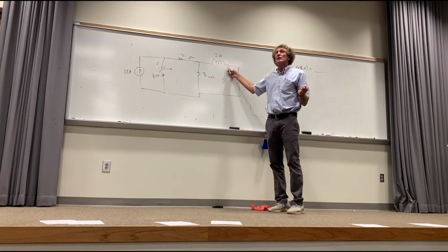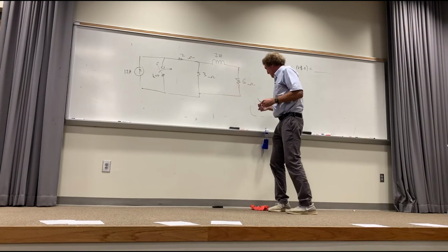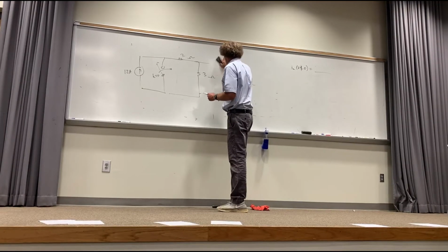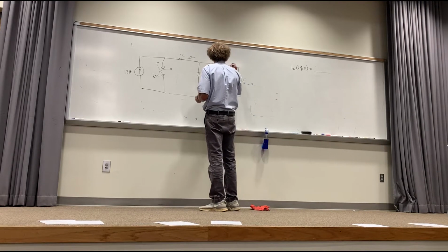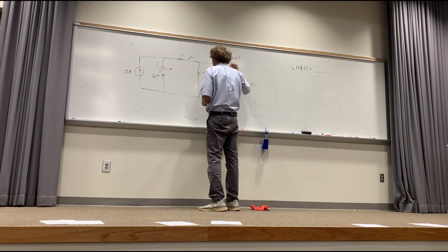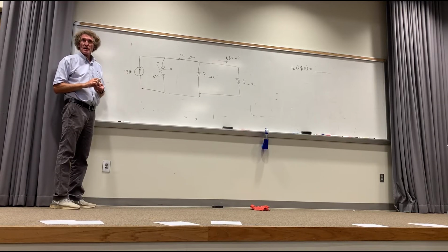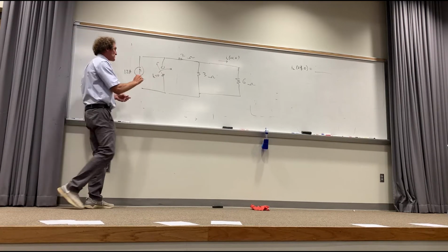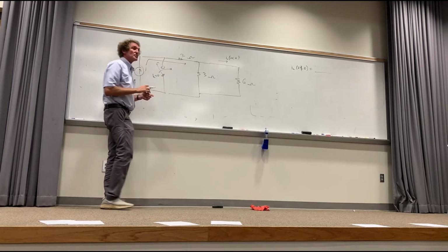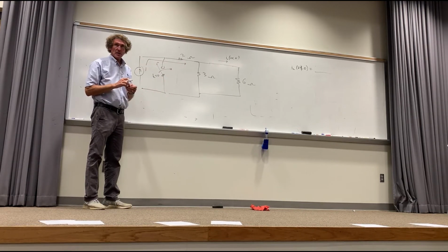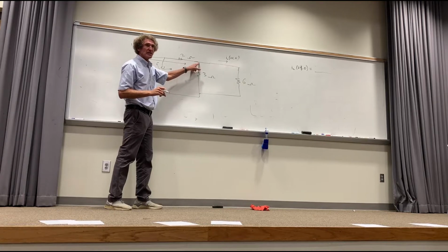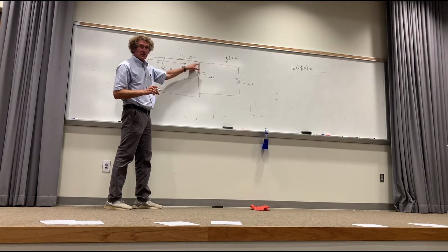Class? Short circuit, a wire, right? Because there's nothing changing with time. Do you all follow me on that? So if that's a wire here, I'll even make it a wire. And I want that current right there, t less than 0. What's it going to be? Now take a look at this, people. Nothing flows through that switch. All that current flows through there. Isn't that right? All that current hits this juncture and then it divides. Isn't that right, class? You all see that?